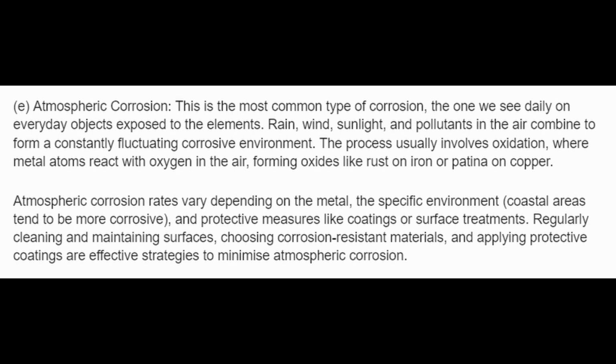For example, coastal areas tend to be more corrosive, and protective measures like coatings or surface treatments help. Regularly cleaning and maintaining surfaces, choosing corrosion-resistant materials, and applying protective coatings are effective strategies to minimize atmospheric corrosion.